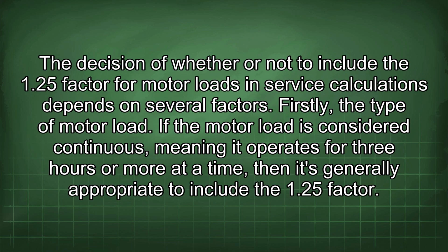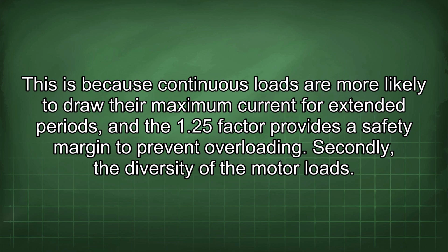The decision of whether or not to include the 1.25 factor for motor loads in service calculations depends on several factors. Firstly, the type of motor load. If the motor load is considered continuous, meaning it operates for 3 hours or more at a time, then it's generally appropriate to include the 1.25 factor. This is because continuous loads are more likely to draw their maximum current for extended periods, and the 1.25 factor provides a safety margin to prevent overloading.